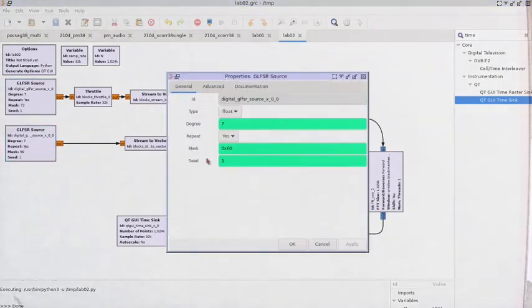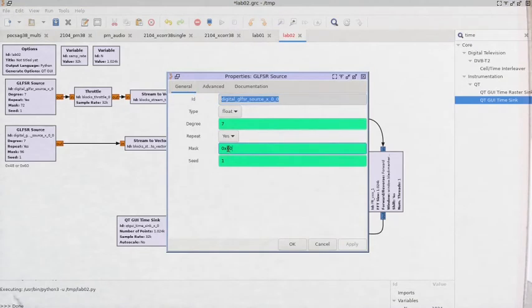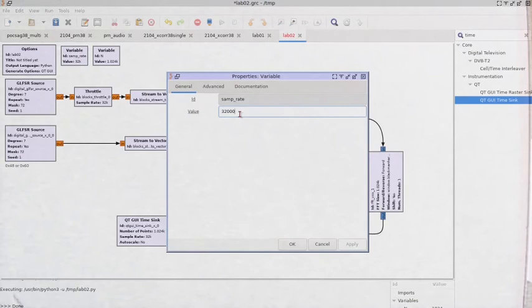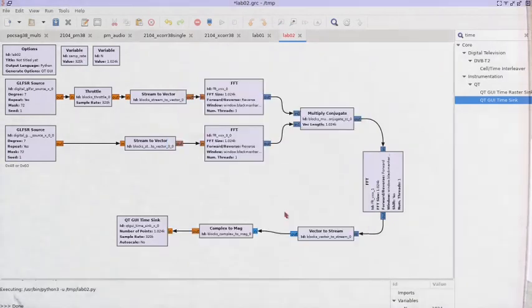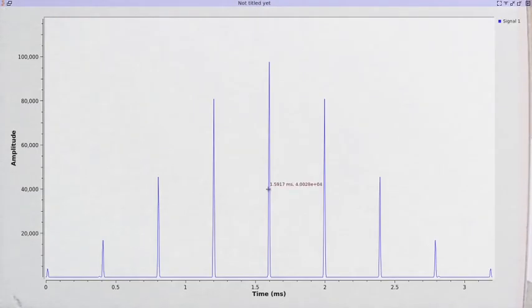So if we now select the same one, and we try to remember which are the two values by putting comments, so the comment is 0x48 or 0x60 as the two possible values. So now we remember what the values are, and we will select 48 here as the pattern, and to make sure that we increase a bit the refresh rate of the output, we can increase the data rate. So here we execute, and if we autoscale, what we see now is we've got this first one over here